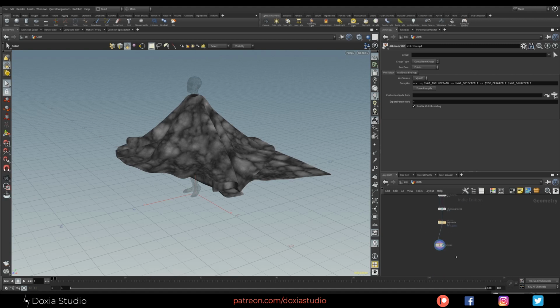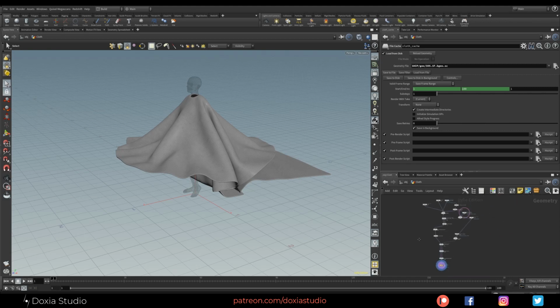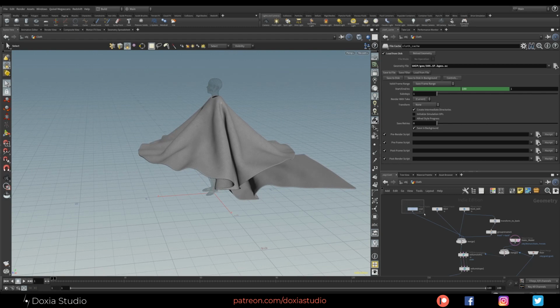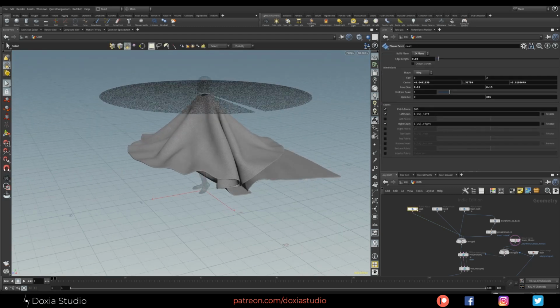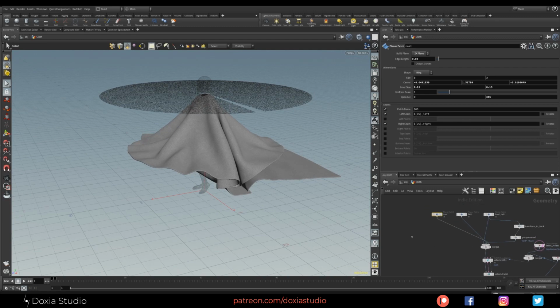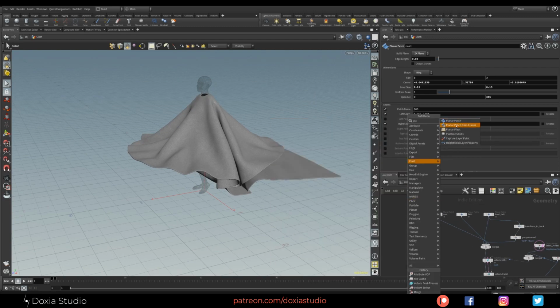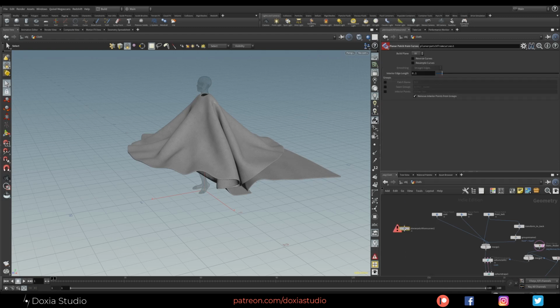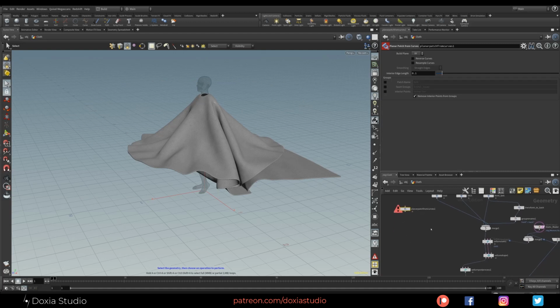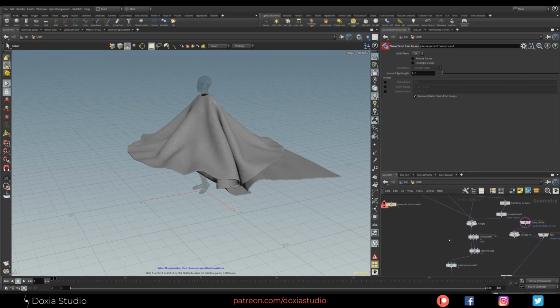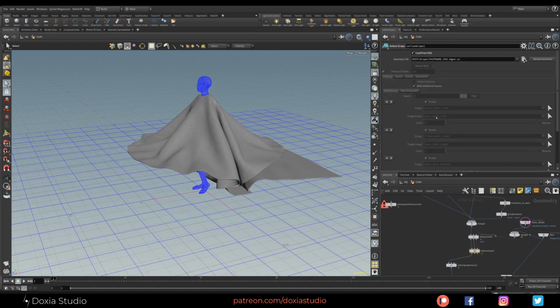Okay, that's it for this tutorial. It was pretty simple. Just one way to create cloth. Now you don't need to go to Marvelous Designer to create simple cloth animation. You can use Planar Patch, use simple surface. As I said, you can draw a curve and then use a Planar Patch from curves. It will make the same as this one, but following a curve. Create groups, point groups to be able to use on drape for seams.